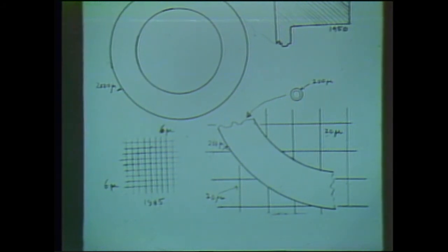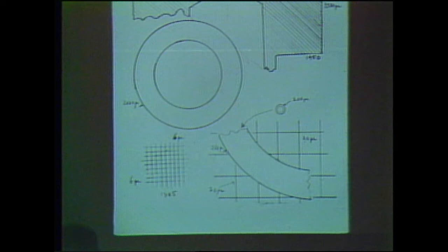Well, now, with a spacing of 6 microns, all the photolithography that you can do with light, because the wavelength of light is roughly 1 micron, when you make things 6 microns, it doesn't really bother you that light is such a relatively gross physical phenomenon.